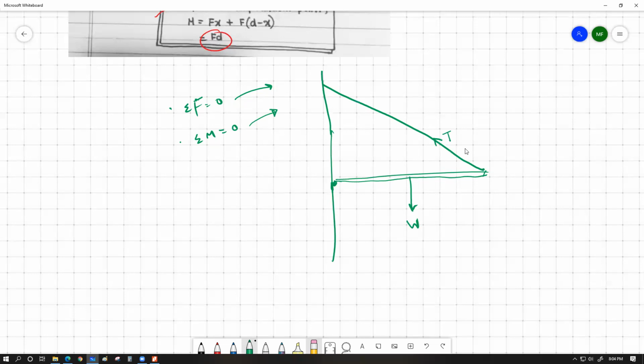Now the question is, can these two forces by themselves produce an equilibrium? The answer is a solid no, because you can see very well that this is a vertically downward force. If we consider that theta over here, a downward force can never perfectly rebalance an oblique force. So these two forces will not produce an equilibrium.